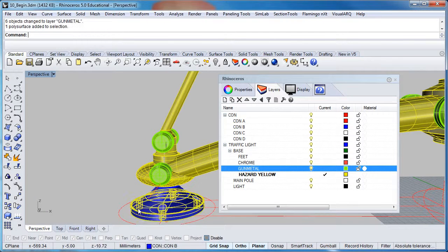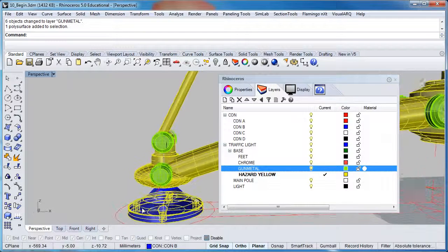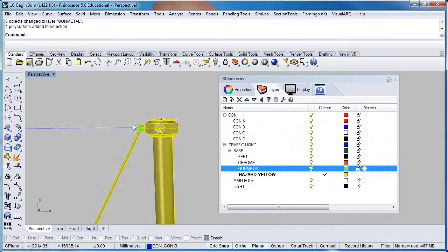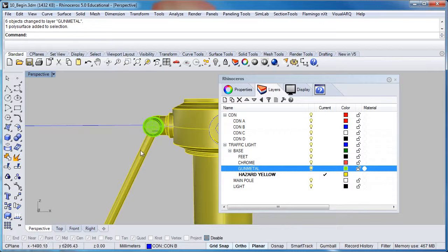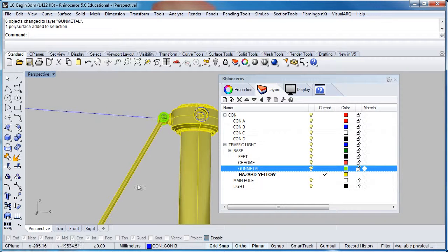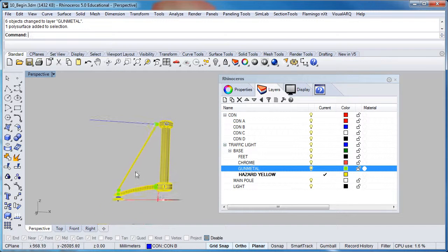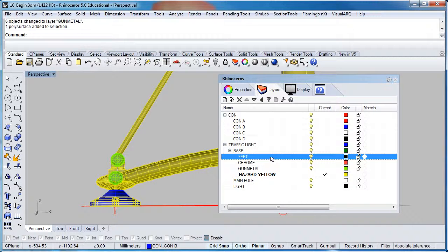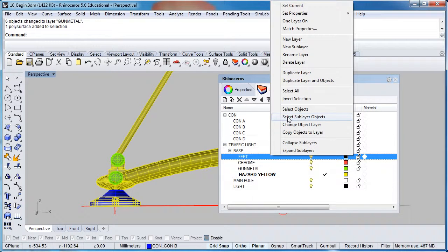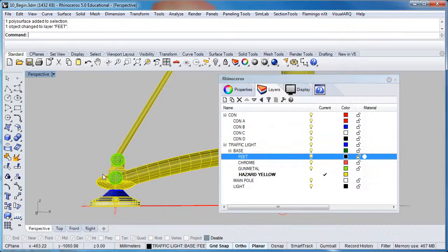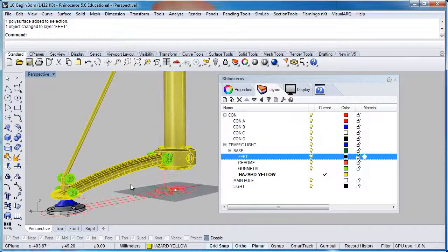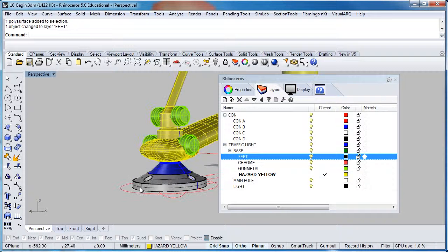We're just going to scroll down, make sure just the foot of the design is going to be a matte rubber colour, so a dark black, charcoal grey sort of colour. So we're just going to shift that onto the foot layer now. That's the only thing I can see. Highlight the foot layer by left clicking on it on the layer manager, right click on the blue line and then change object layer, and then confirm that what you think you've done is actually demonstrated on screen.